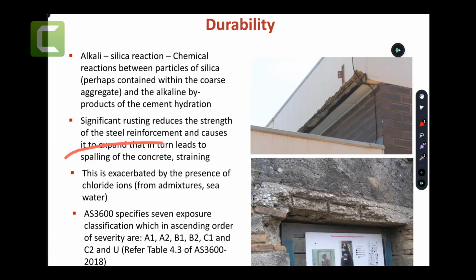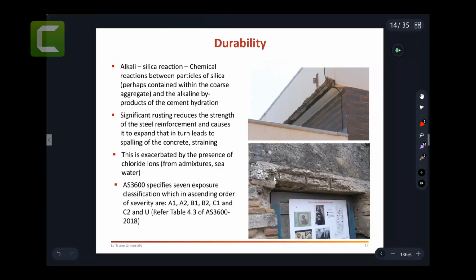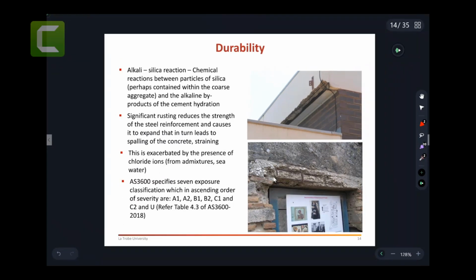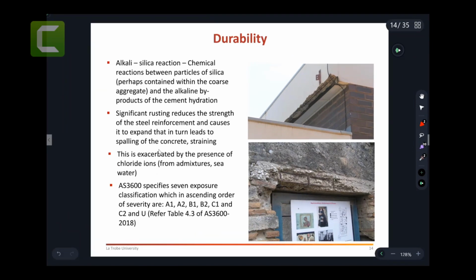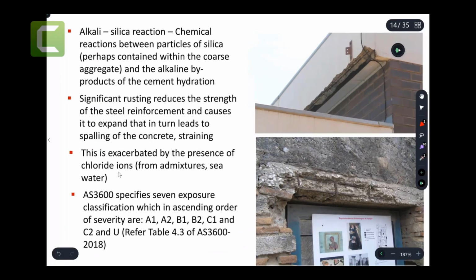It's just the aging, and even as a designer engineer, you're only going to provide insurance for 10 or maybe 7 years, but usually the owners need to maintain their structures, or whoever the stakeholders are, whoever looks after a building. So any crack due to shrinkage or due to impact, whatever, should be treated accordingly, and things will stay durable for the expected years.